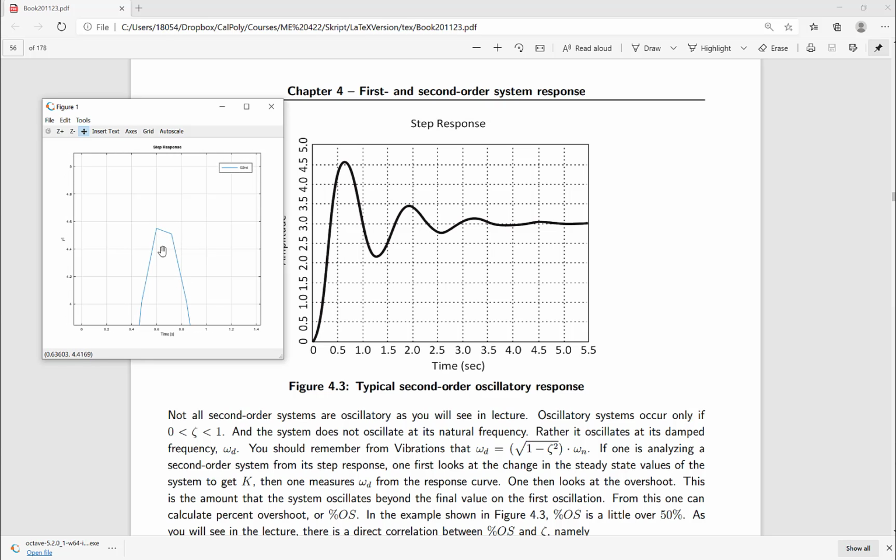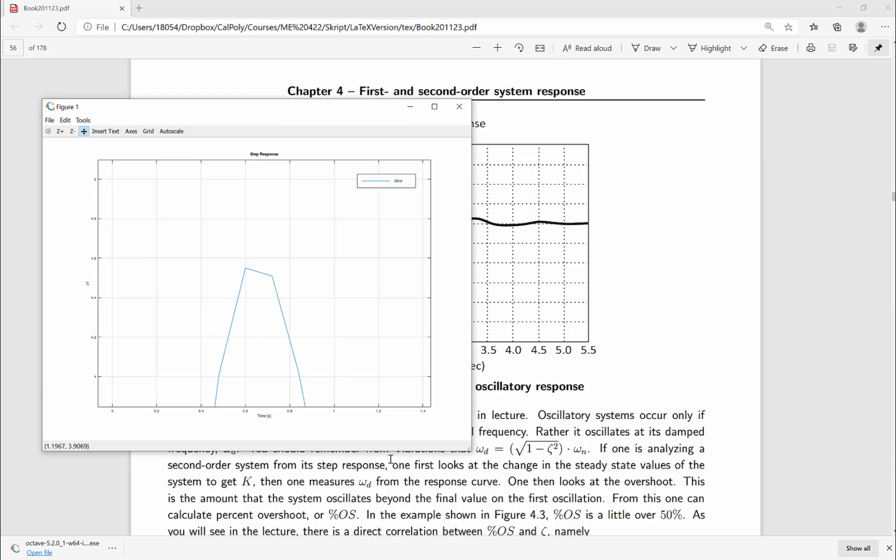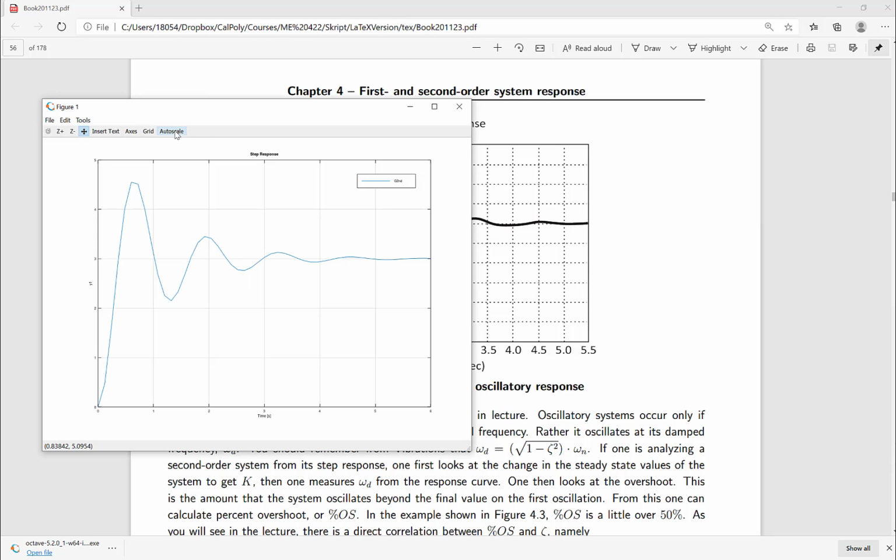The time steps in the calculation look like they're going from, let me make this a little bit bigger. This didn't help a whole lot. That's 0.4, that's 0.6, that's 0.8. So they're jumping quite a bit, and we need smaller time steps. Let me scale this back out.